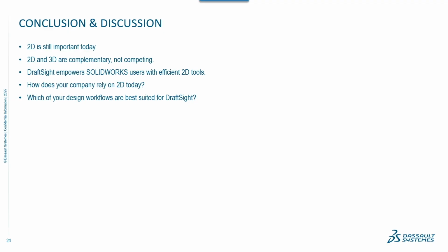So I didn't really cover that because I felt like for somebody who had used SolidWorks, obviously that's a good use case for creating not only DWG files from drawings, but also DXF files from flat patterns, things like that, that you want to do in SolidWorks. Sometimes I know you have to clean up those DXF files. Hopefully if you got the settings right, maybe you don't need to, but that's another use case as well for 2D out of the box. Anybody else? No?